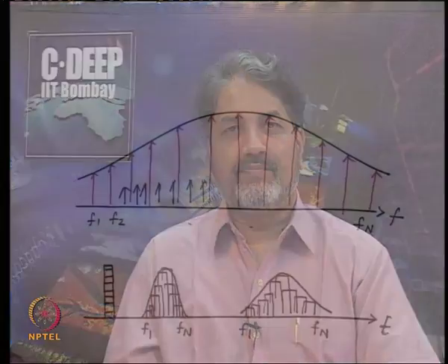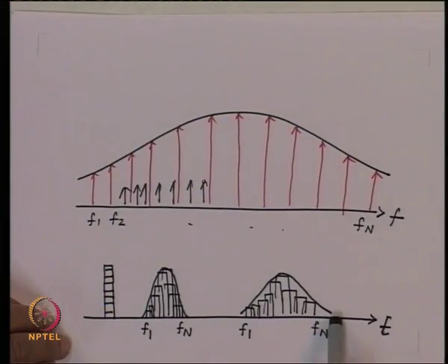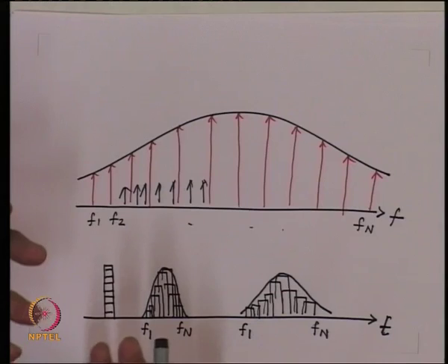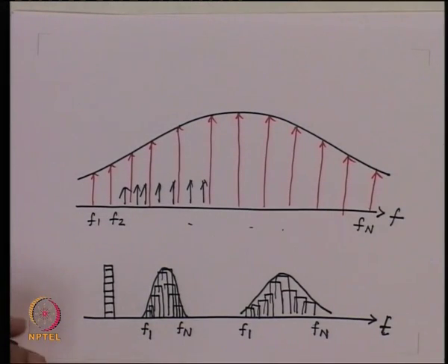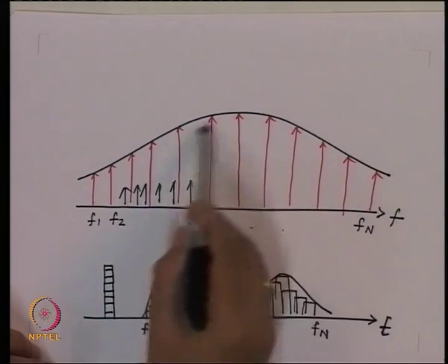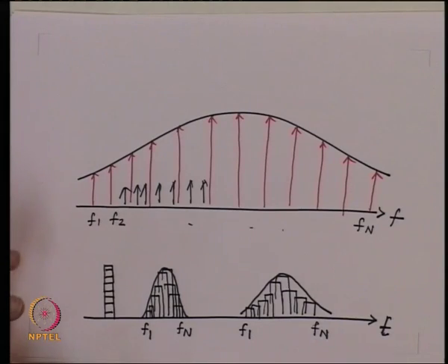Secondly, more interestingly, we also see that the shape of the signal in the radio system has a relation to the modulating signal which you originally sent, whereas when you come to the optical system, we find that this shape, at least after a certain distance of propagation, has nothing to do with the original pulse which you transmitted, but is decided again by the carrier spectral profile.